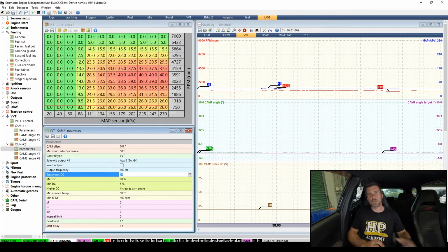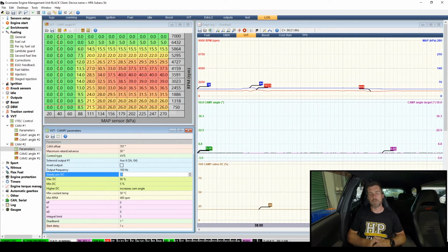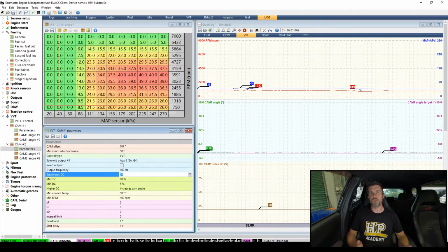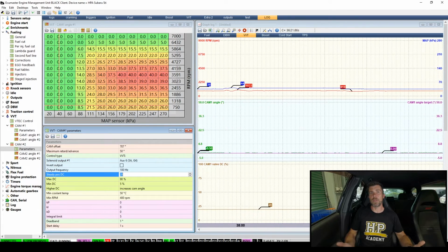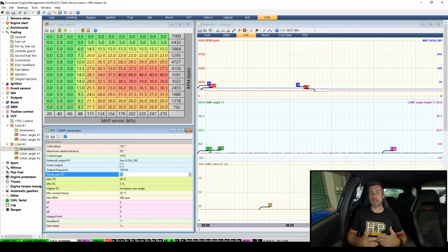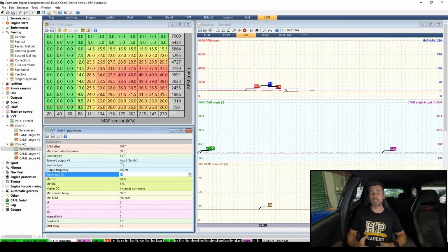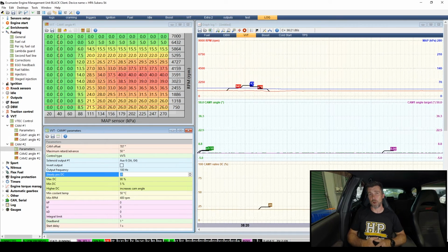What I'm going to do is we'll just get ourselves up and running here, maybe between 2 and 3,000 RPM, just to give us enough oil pressure, and we also want to make sure that before we do this test or our PID setup, our engine is in fact up to operating temperature, and more importantly that we've run the car long enough to get good temperature into the oil. Given of course that the cam control system is oil driven, it's important that the oil is under what we'd consider at least close to our normal operating conditions. Let's get ourselves up and running now.